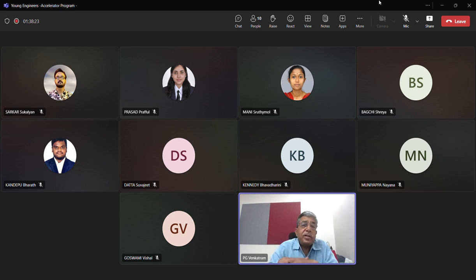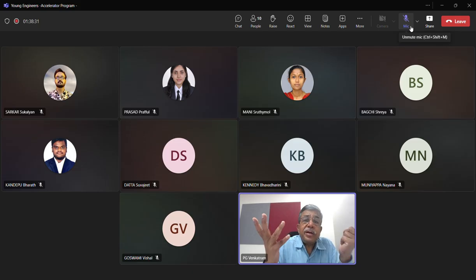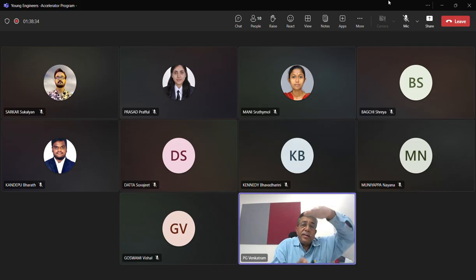Now, when it comes to the vertical direction, your piers are very stiff. You agree? There is no pier flexibility at all, because under axial compression all columns are very, very strong, unless they have a significant buckling potential, which we don't want to have.